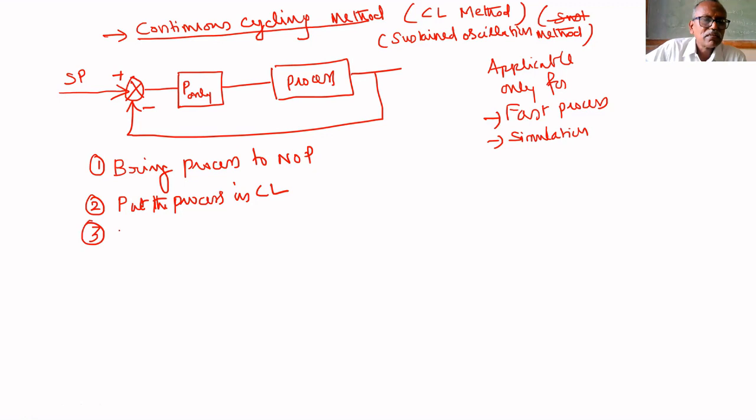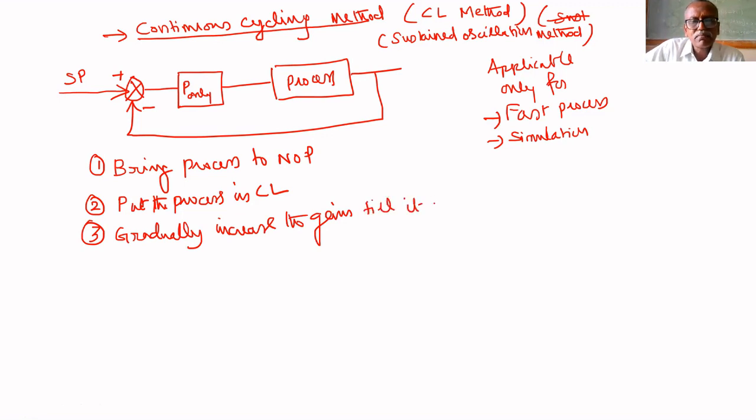Third point is to gradually increase the gain till it exhibits sustained oscillation.